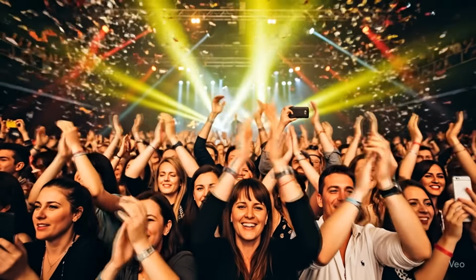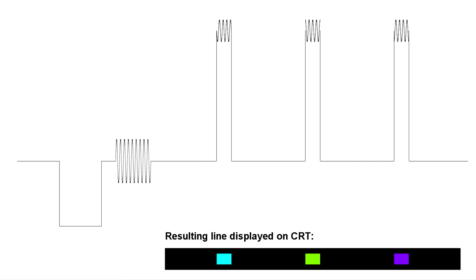The same kind of thing happens with the TV signal. First, as usual, the horizontal sync pulse is sent. Then we add several cycles of a color burst signal. This is the band leader clapping, teaching the TV the beat. And the beat is fast, 3.579545 MHz, the same frequency as the chroma signal. Then the color burst just stops. But it's enough for the TV to keep on clapping, and that is the reference signal it uses. Once the chroma signal starts, the TV compares the phase of chroma with the phase of this reference signal. The difference determines the hue.